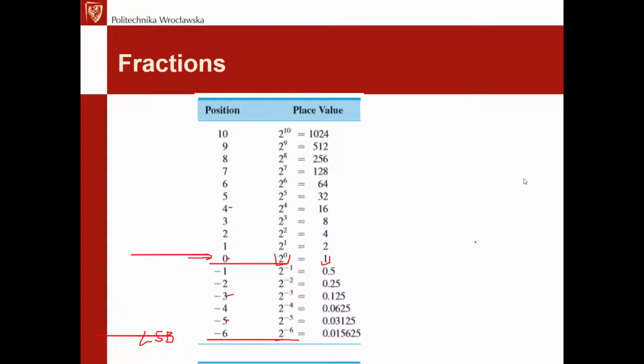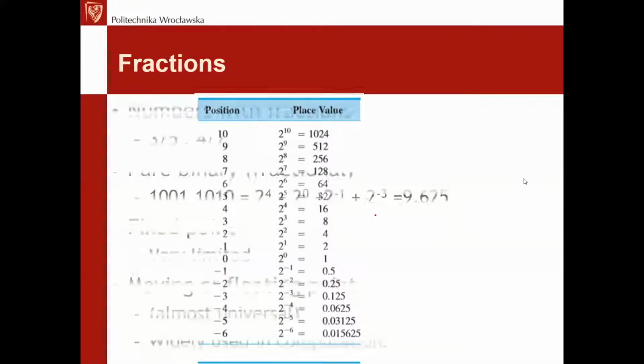Yet it has pretty decent advantages. The major advantage of the fractional method is that we are using a very similar arithmetic to the integer arithmetic that we spoke about, and that we'll be analyzing a bit further, for multiplying and division, for example. So the same arithmetic and the same calculation units, various logic or arithmetic units, can be used when dealing with fractions, because fractions behave similarly. It's just about how we read it and how we decode the binary.